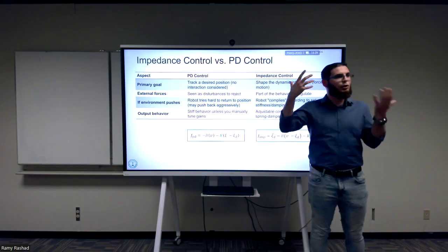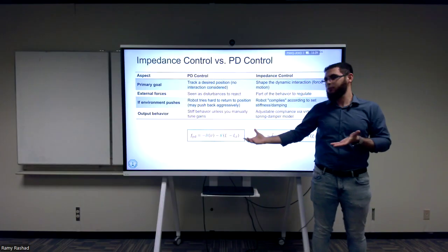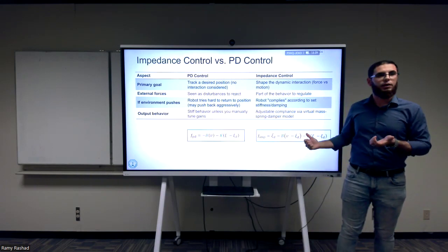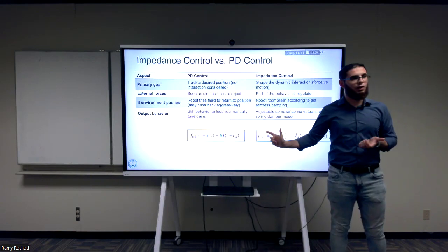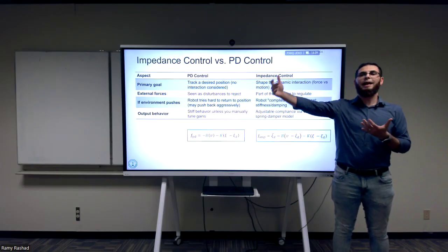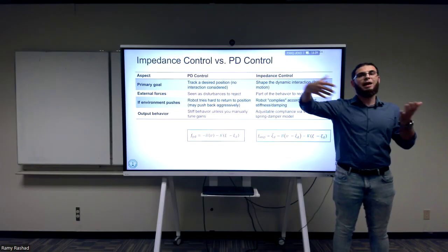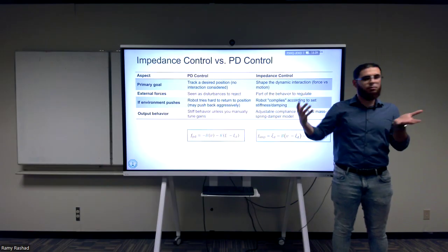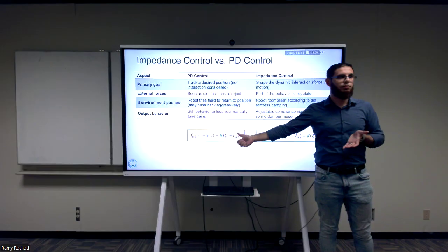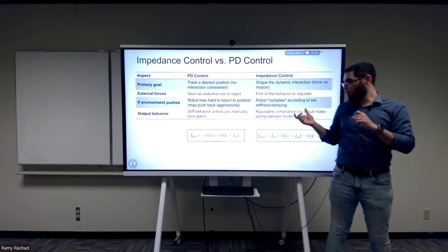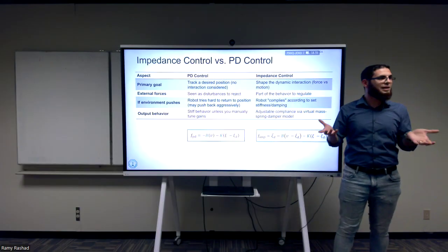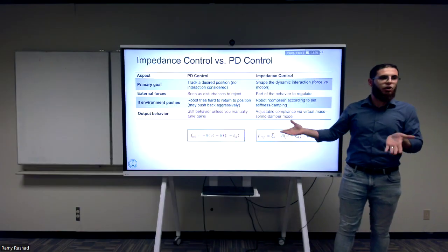But when we looked at it from a potential point of view, we managed to extend it and things worked on SO(3). The same also here. When you think of the impedance controller from this perspective, and then think about the complicated case, which is 6-dimensional springs and 6-dimensional inertia, this will work, but thinking of it the other way will not. So don't be deceived by the fact that the controllers look exactly the same or very similar. Actually, they are the same.